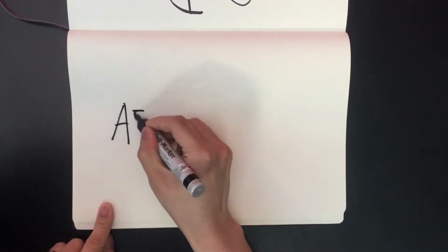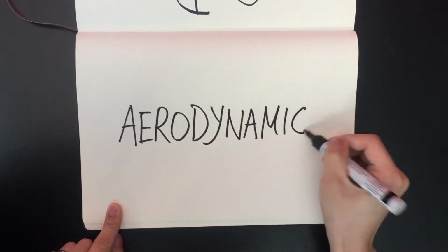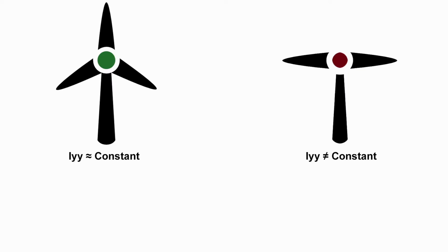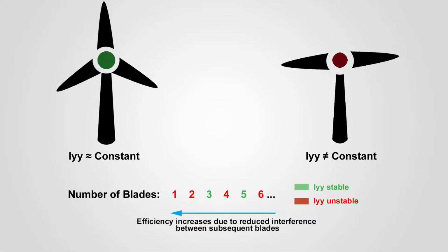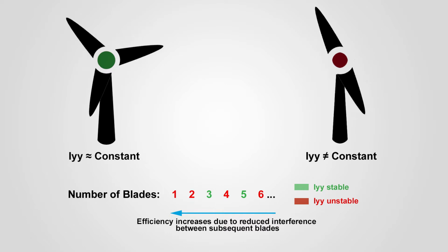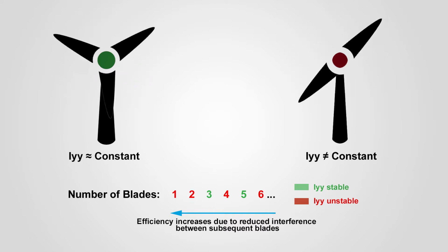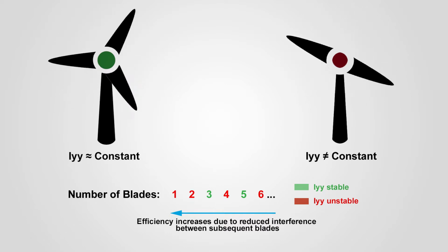The first decision to make when designing a wind turbine is the number of blades. Usually, an odd number is chosen since it guarantees constant moment of inertia about the vertical axis, reducing the vibrations on the tower. In this case, a two-bladed design was preferred due to the size constraints and to simplify design and manufacturing processes. Once the number of blades is known, it is time to look for an airfoil.